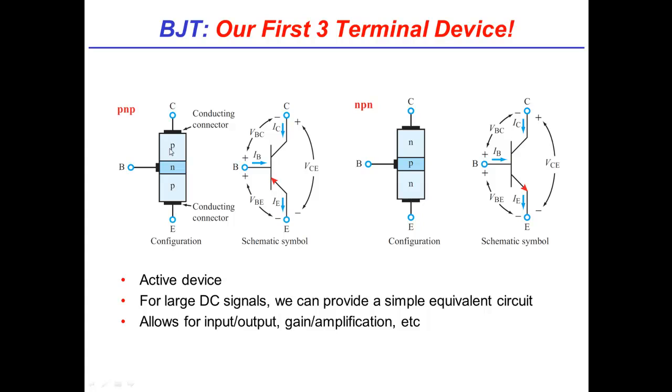So to give you just a little bit of background here, you see those things labeled N, P, and N? Well, that entire stack is a block of semiconductor material. For example, it could be silicon or germanium or gallium arsenide, what have you. And each of those is a region within the material that is designed to conduct in a particular species more dominantly. So, for example, N will have an excess of electrons, and the electrons will tend to be the dominant conductor within it. P has an absence of electrons, and so effectively there's a net positive charge, because there's an absence of electrons that becomes the dominant conductor.